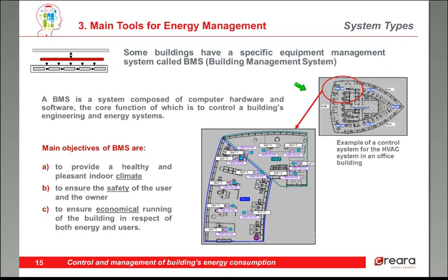management system, which is called BMS, or Building Management System. This is essentially a combination of software and hardware, which allows a good control of the equipment installed in the building. The main objectives of a BMS are essentially keeping a healthy and nice indoor climate, ensuring that safety is guaranteed, and trying to run all the operations of the building in an economic way.